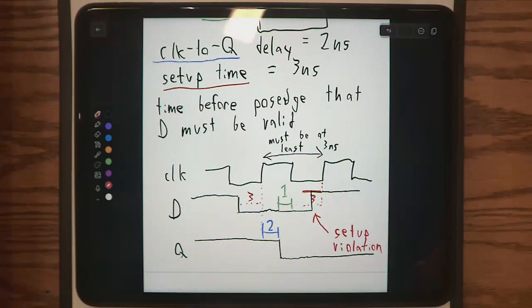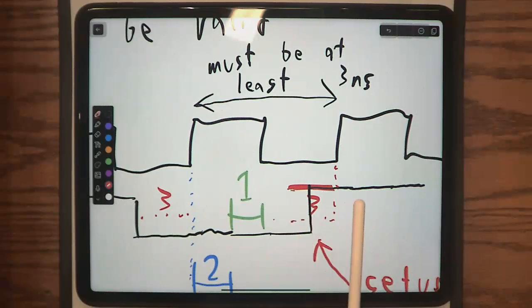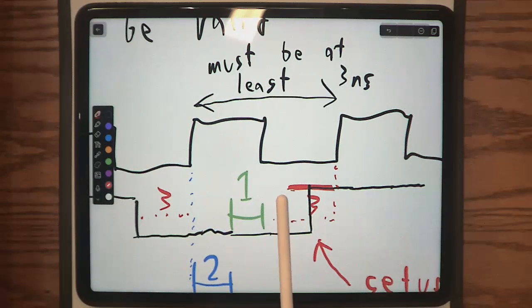Yeah. So this is cool. I want to show you another characteristic of flip-flops. Things get a little bit confusing at this point. I'm going to try a different explanation than I've tried in previous quarters, so hopefully it'll be a little bit better now. But I've been lying to you just a little bit, because I'm assuming that the setup time is how far in advance of this positive edge that D needs to be held for.